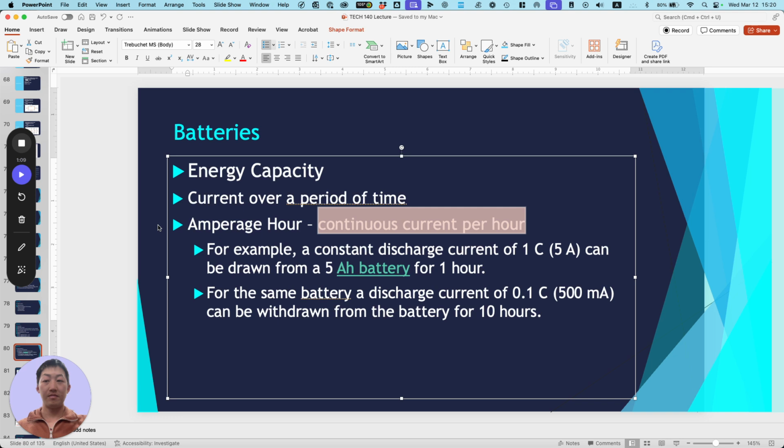The next cell, you're going to put it on the negative of the previous one and the positive of the next one. And then the next one, you're going to put it on the negative and then the positive. So that's why just on the first cell alone, you already have 2 cables coming out. And then the last cell, you also have 2 cables. Here, let me just show you the image.